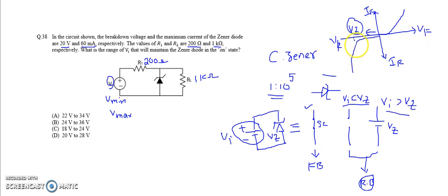That is what happens at the breakdown voltage, because at that reverse biasing voltage the maximum number of covalent bonds break down and a huge number of free electrons are released, so there is a sudden increase in current after the Zener breakdown voltage.